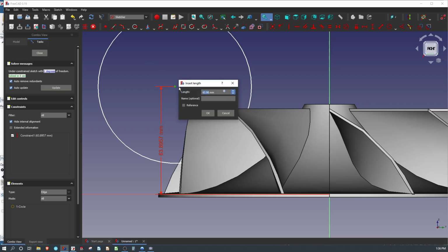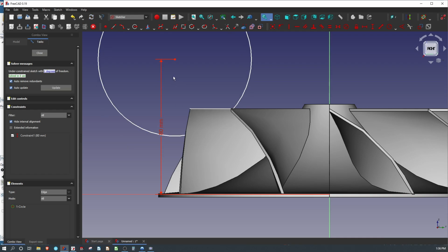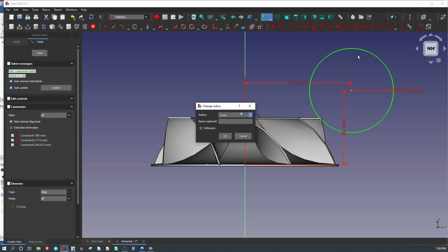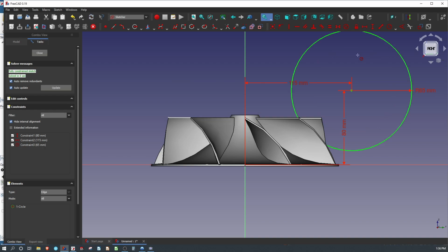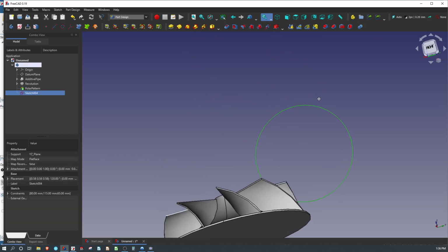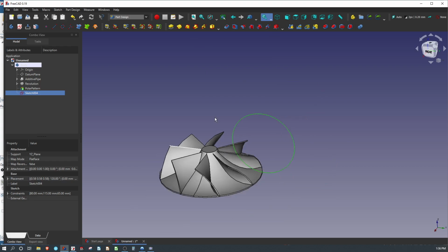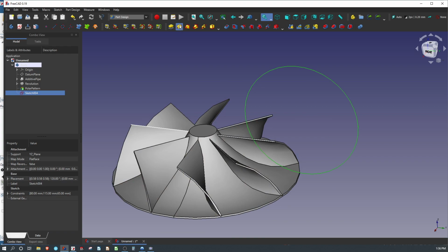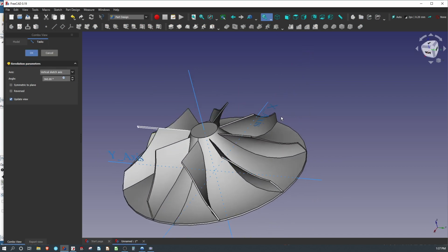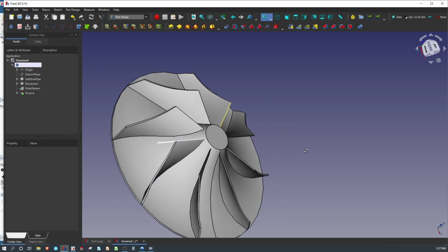And we're going to say Shift V for 80, Shift H for 115, Shift R for 130, but we're doing a radius, so we divide by 2. Then we'll close. Now we don't have the surface work that we're doing, so this remains a circle. We don't have to worry about that little anomaly that we saw. So now we can simply say remove revolve or simply groove. And what do you know? It knows what axis we want, so we're able to get that pretty quick. Fantastic.